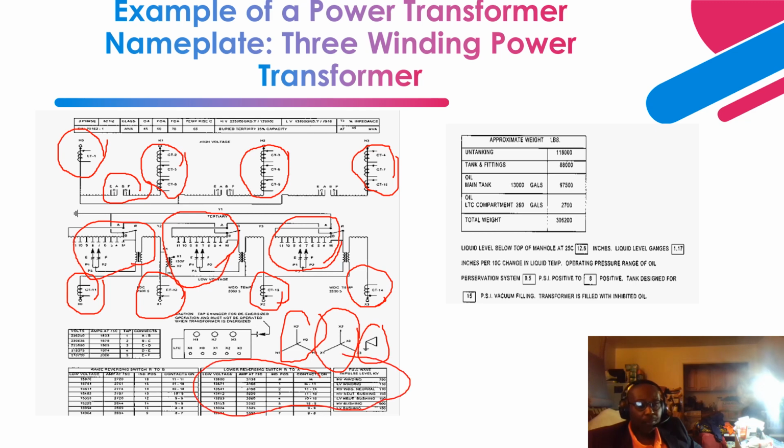Also shown over here. And for the high voltage side, all the 5 taps are shown: tap 1, tap 2, tap 3, tap 4, tap 5, with tap 3 being the nominal tap. So you have 2 taps above and 2 taps below. Taps 1 and 2 are above, and 4 and 5 are below, with tap 3 being the nominal. Nominal means that is where it's going to show you your nominal voltage. So if the nominal voltage is 115 kV, tap 3 will give you that indication.